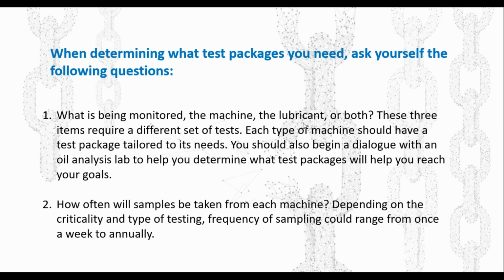The second question you want to ask yourself is, how often will samples be taken from the machine? How often can they even be taken? When we talk about wind turbines, obviously you're only climbing those towers twice a year, if that at times. So you also want to look at the criticality and the type of testing, and the frequency of the samples, in order to help you determine the best test slate for your machine.